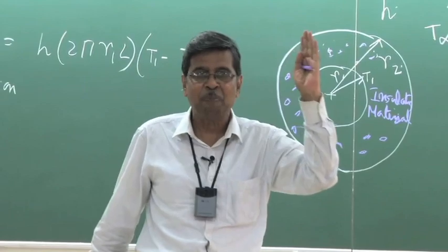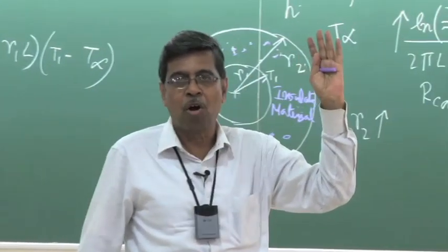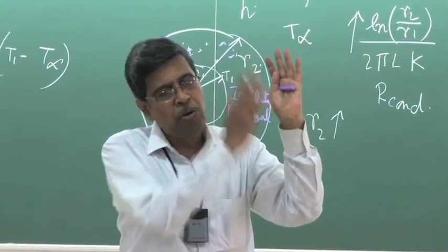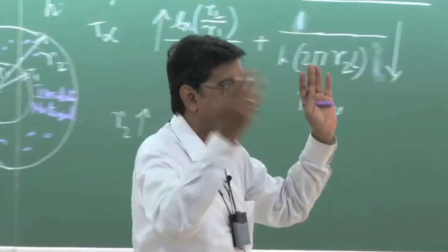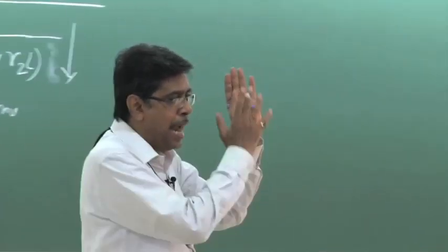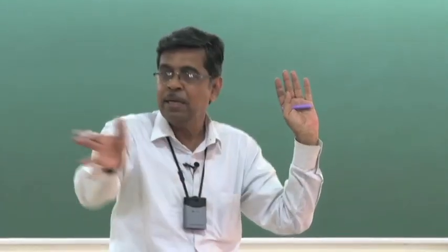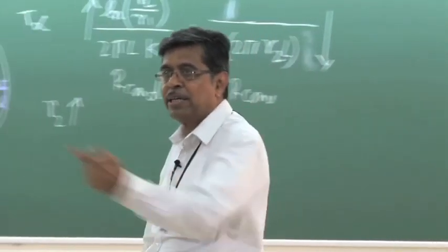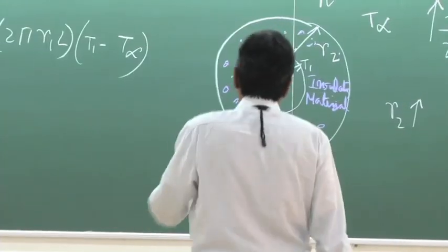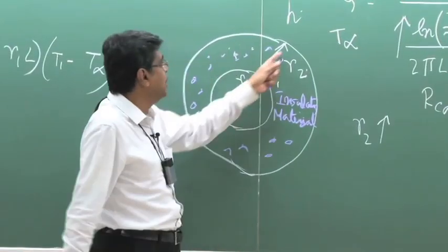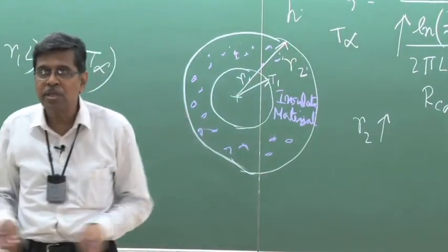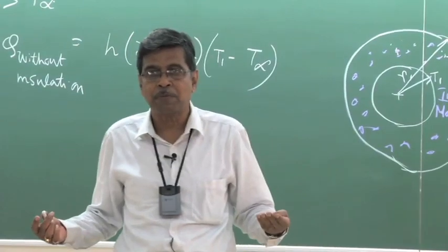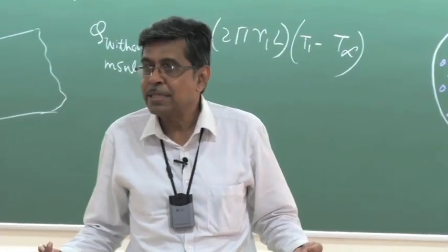It doesn't happen on a plane wall. There, Q is a monotonically decreasing function: the resistance will always increase if you go on adding the insulating material, because the surface area is independent of the length or direction along which heat flows. But here, if you increase the length of the heat flow path, the surface area also increases, so convective heat transfer from the outer surface increases.